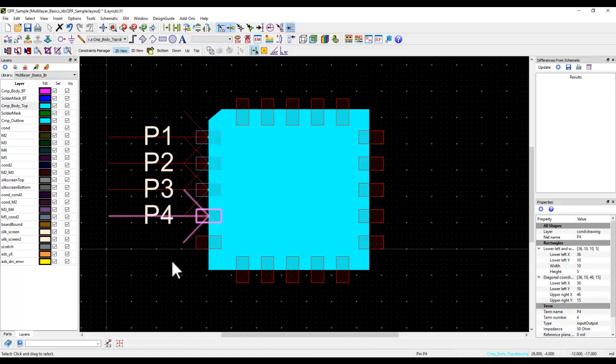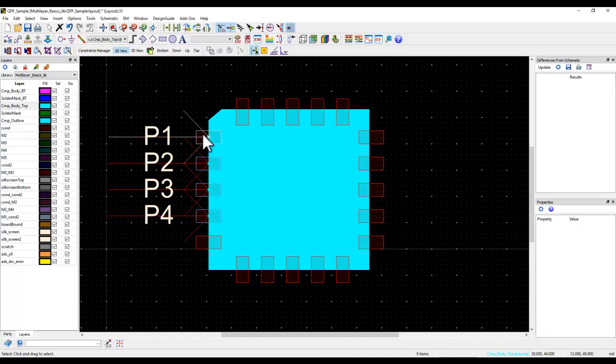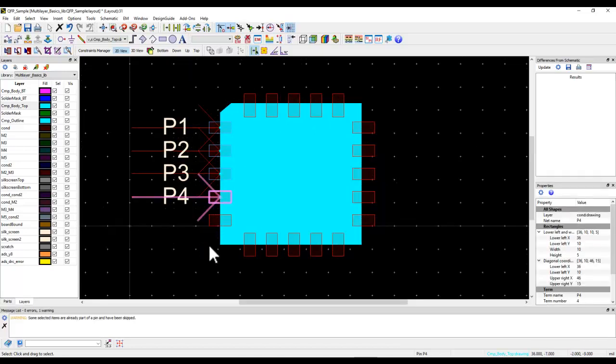And here, sometimes you need a good starting point, and having a little bit of ADS symbol generator knowledge will come in very handy, because ultimately we will have a schematic symbol which will represent this in a schematic design. If I am going to use the default symbol generator in ADS, that's how the nomenclature starts. It always has pin 1 here, and then it goes anti-clockwise. So here, just to help myself, I'm using a similar configuration. If you don't select the pad and you press Alt Q, it says it already has a pin. So not a problem, we can always click correctly. And here, let's keep on doing that very, very quickly.